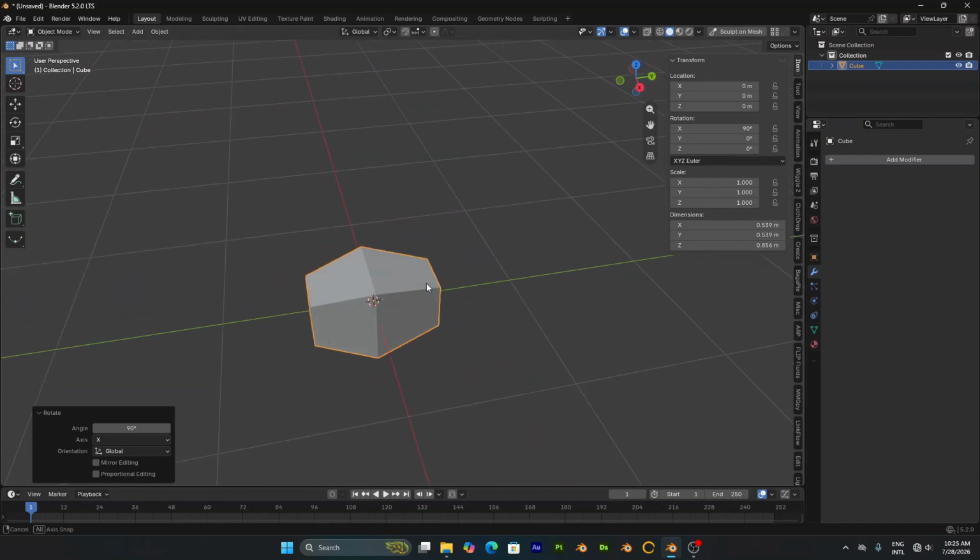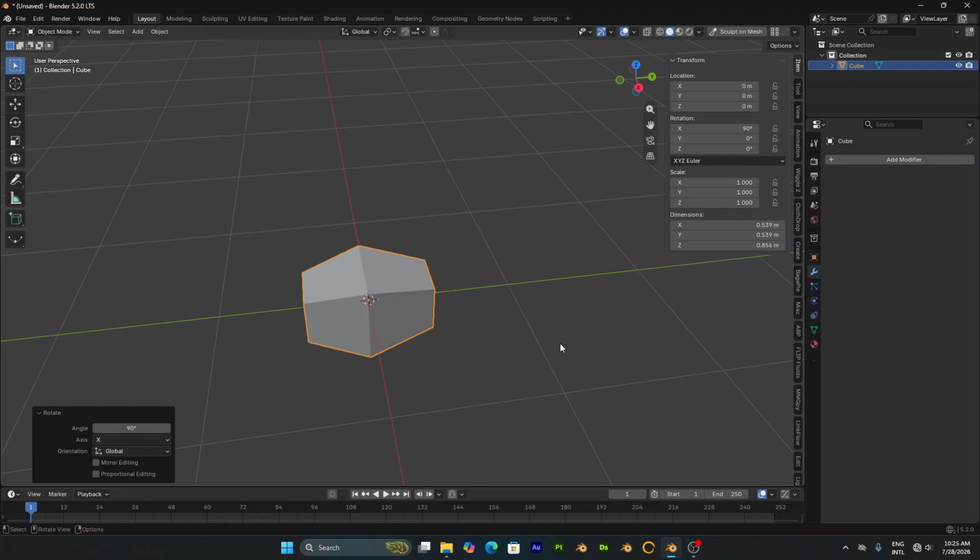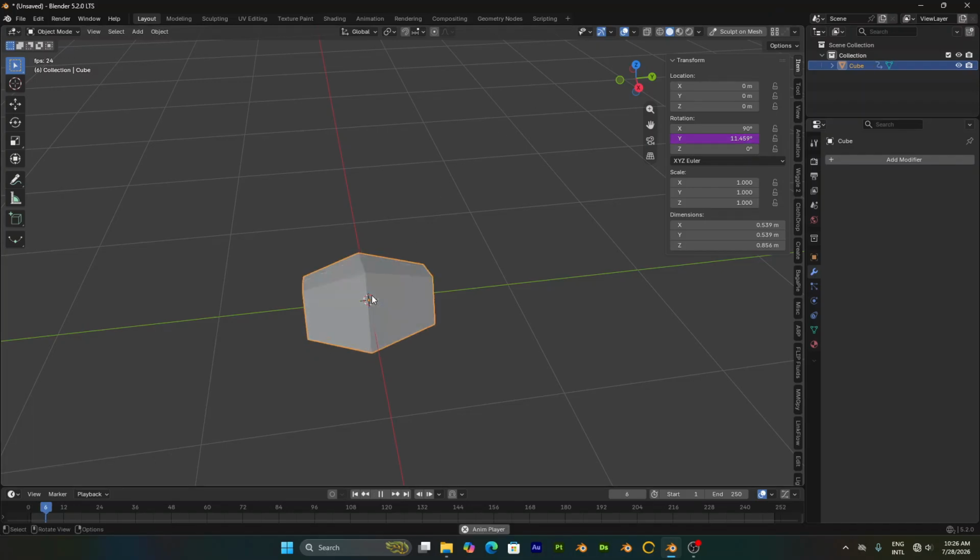Okay, now I'm going to animate this without any keyframes. So I'll use drivers. Now go to the M panel and then click on the Y rotation and type this: hashtag frame forward slash 5, and then press enter. Now press play to see the animation.